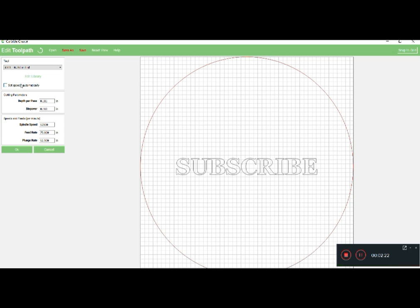So here is our set speeds automatically. Depth per pass is how far we want it to go down every pass, and you don't want to go crazy with it. I think this is good, the 0.111. I don't have an issue with that. If you want to bring it up higher or lower, that's fine.